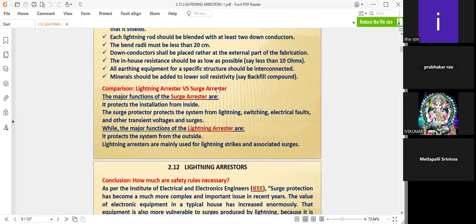Normally 90% of organizations decide on lightning arresters for their premises. But where the circuits have very sensitive electrical equipment, surge arresters will be installed within the circuit itself rather than lightning arresters above the building. The circuit itself takes off the current and immediately saves the equipment, so the whole area is safe.